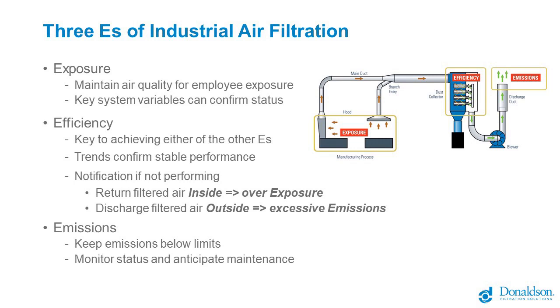In terms of emission, the goal is to keep the value below the regulated limit, whether it's total particulate, PM10 or PM2.5. Monitoring the status of your system over time can help you anticipate maintenance and predict if there are any issues developing. When it comes to exposure, you want to identify what's in your airstream. Knowing the particulate, whether it's filterable particulate or a gas, will help identify the level of control that is needed. This will impact on system design details, such as the hood or the airflow that's required to remove the hazard from the employee's working area.